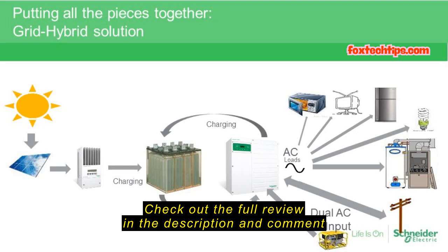So one thing that is definitely worth looking into to add on to the system would be the furnace as well as the hot water tank heater, if they're run by gas, because the power consumption for those is fairly minimal when we're not using electricity to generate heat. Not a good idea in general to try to heat hot water or heat a house with electricity during a power outage. You're suddenly looking at a very, very large battery bank.